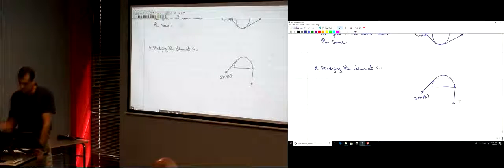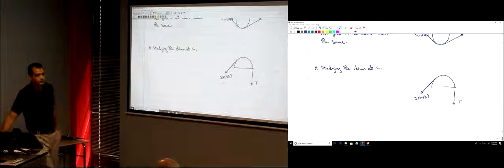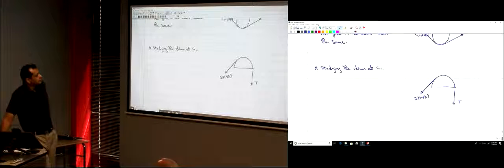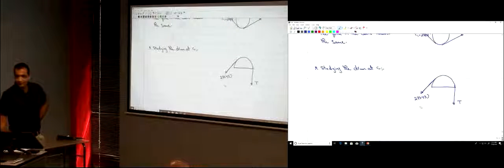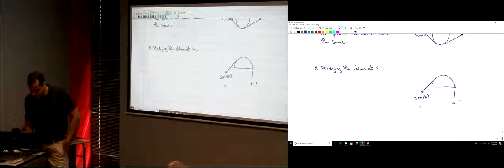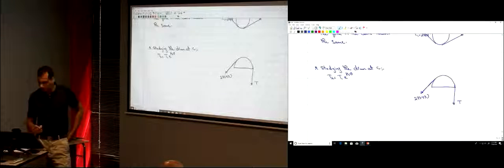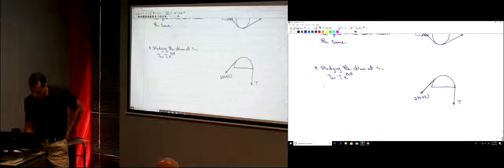We want to find this force T. Now we're calling this one T1, so don't get confused. The equation says T2 equals T1 e power mu theta, which is the larger one. But T1 is going to be less than 277.4, that tensile force.